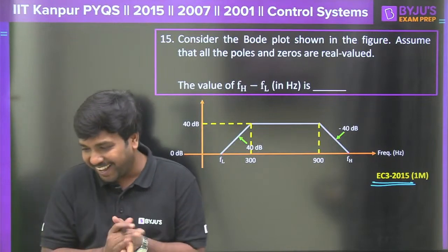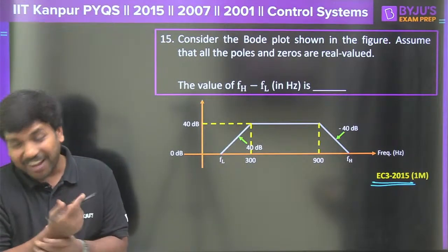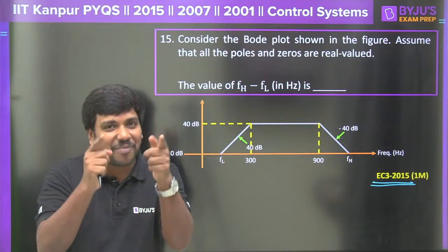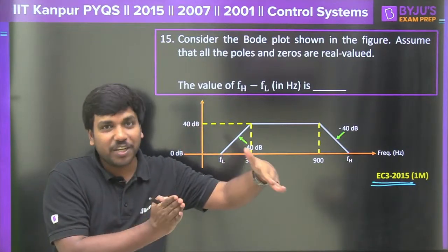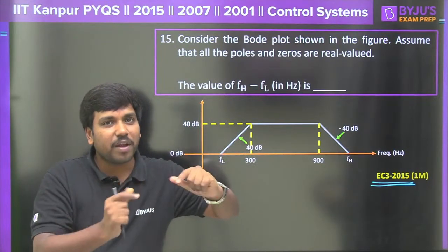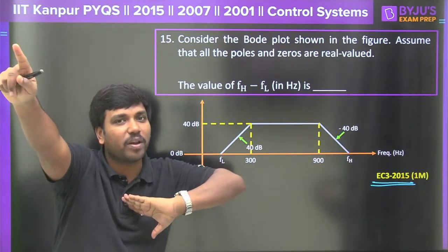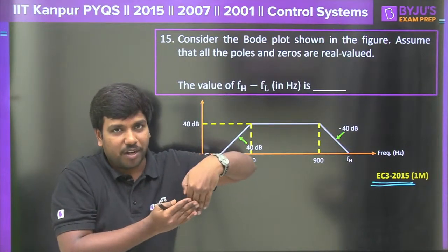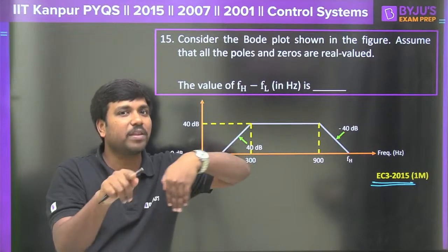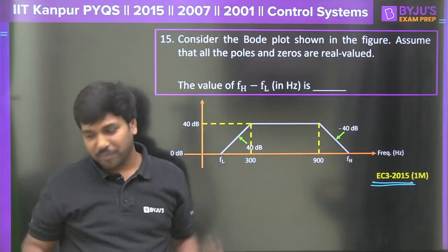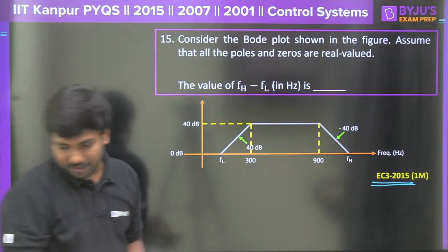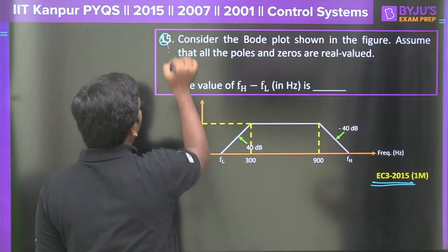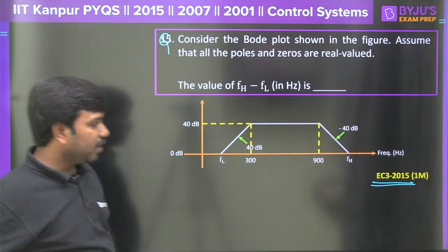Formula gone. Rajesh, that's why I'm saying clearly every time, more than formula, you need to keep your mind attentive. Okay, minus 216 you got. What does it mean? Phase margin means anything if you go beyond minus 180 degrees, you will be struggling. You should always be less than that minus 180 border. So you crossed means phase margin is going to be negative. This is the way you should think. Don't use the formulas more and more. Formula is required, at the same time you require the concept also. That is what I mean to say.